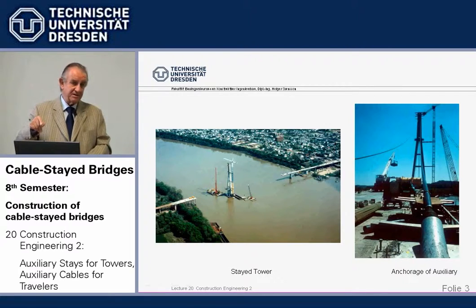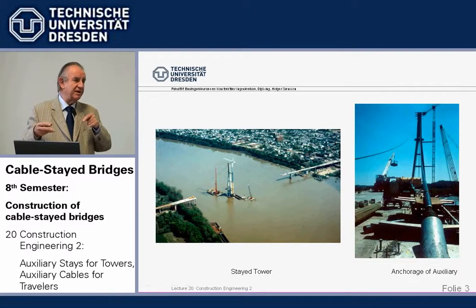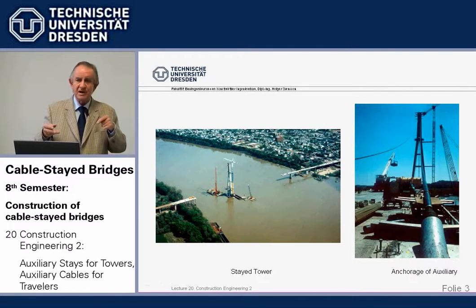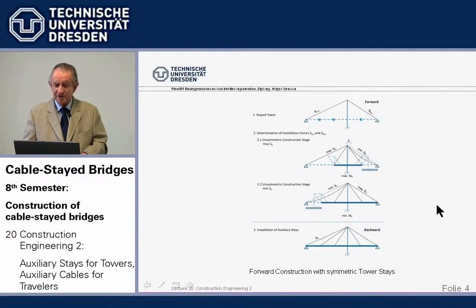During construction, we very often have to take into account the change of sag, the change of E modulus of the tower into effective E modulus, change of sag because the stresses change much more than in the final stage. You remember 7th semester I told you effective modulus of elasticity, stress to the power of 3. Now that comes in here, but that's a minor point.